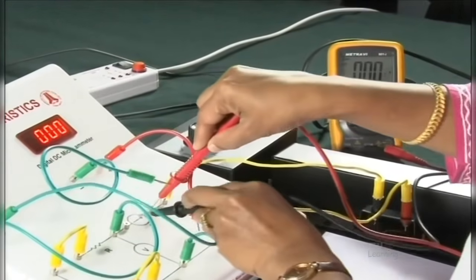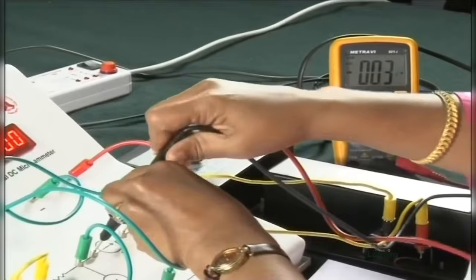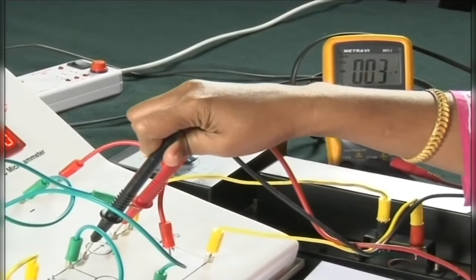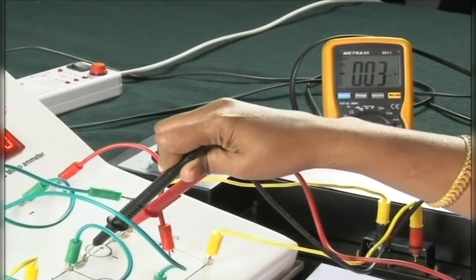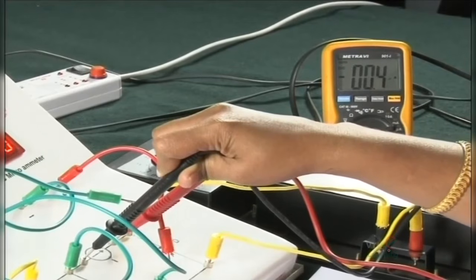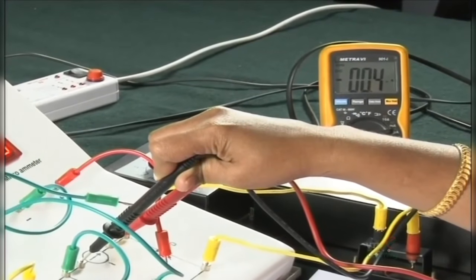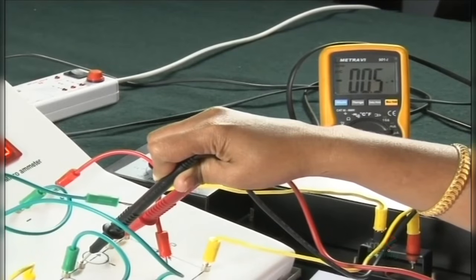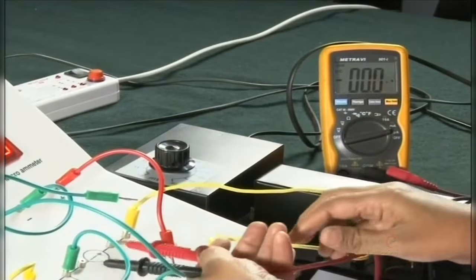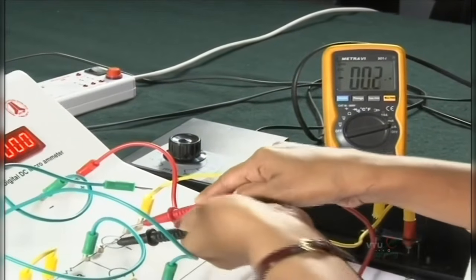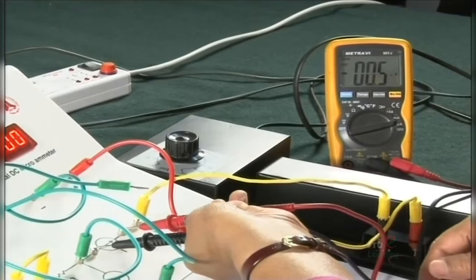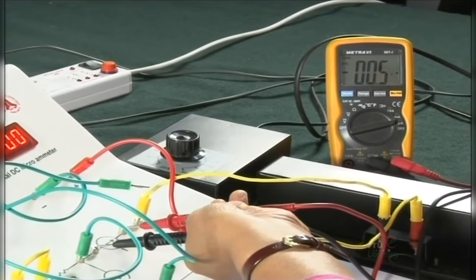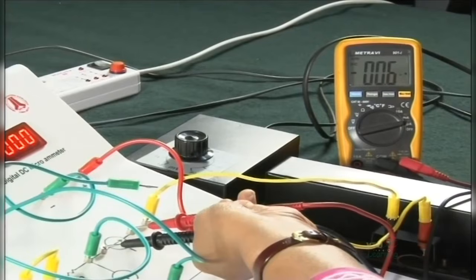A very small current for the variation of voltage, of the order of 0.3 microamps. Very small, and it remains almost constant, 0.3 or 0.4 microamps, a very small current called dark current when the illumination is off. So with no illumination, the corresponding current is referred to as reverse current, called dark current, in a photodiode.